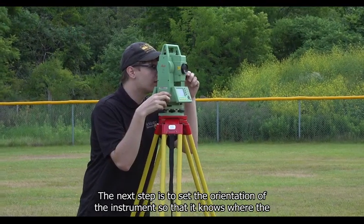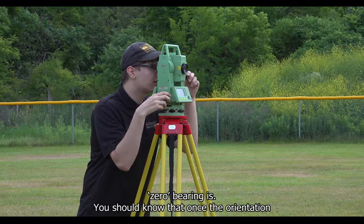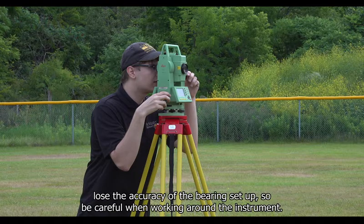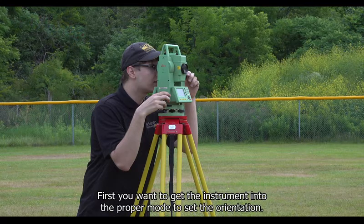The next step is to set the orientation of the instrument so that it knows where the zero bearing is. You should know that once the orientation is set, if you bump the tripod, or the instrument, or both, and knock them out of level, you will lose the accuracy of the bearing setup, so be careful when working around the instrument. First, you want to get the instrument into the proper mode to set the orientation.